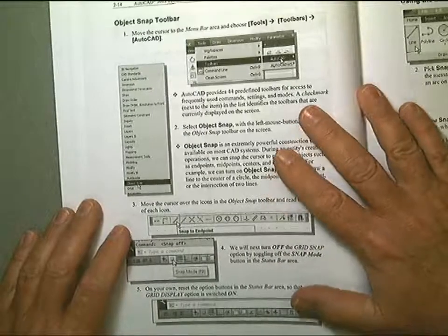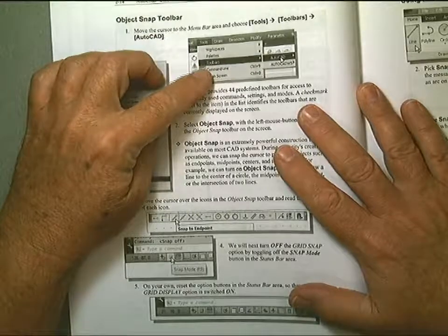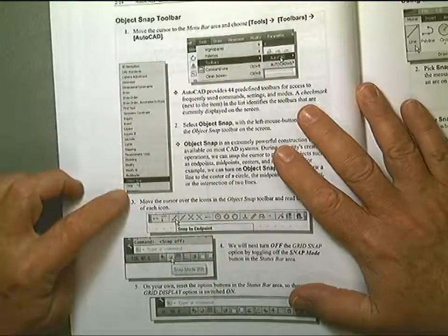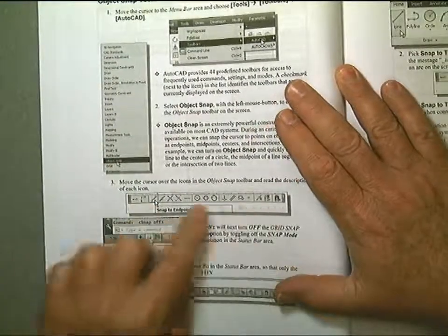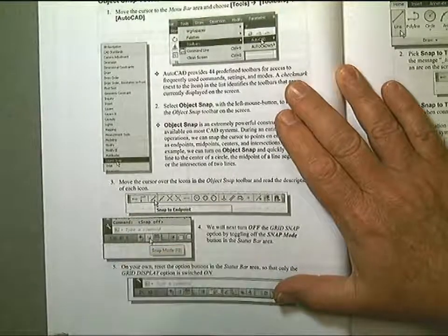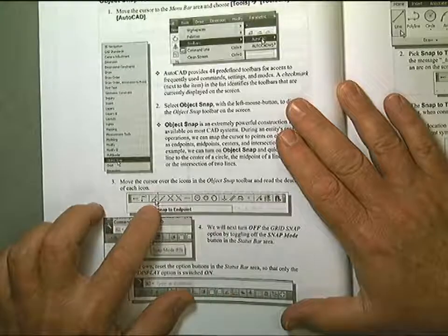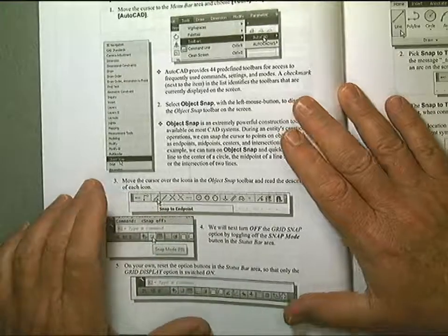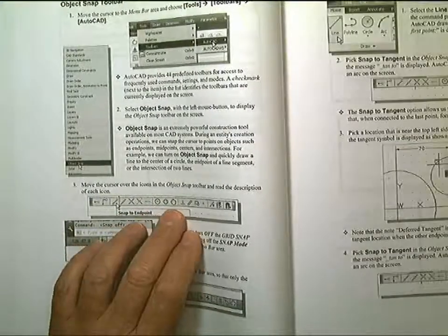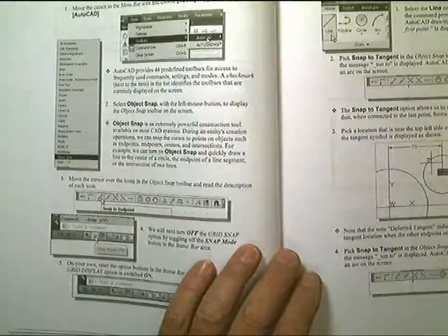Your Object Snap toolbar, which you can access by turning on under Tools, and then Toolbars, and then AutoCAD, and then look down the list and find Object Snap. So you'd want this turned on and anchored to the top of your screen or somewhere that's convenient. Therefore, you can pick different geometry snaps, which we'll be using endpoint primarily, to be able to attach, or to center, or to the quadrant, or to tangency. So lots of different object snaps or geometric snapping that we can do.